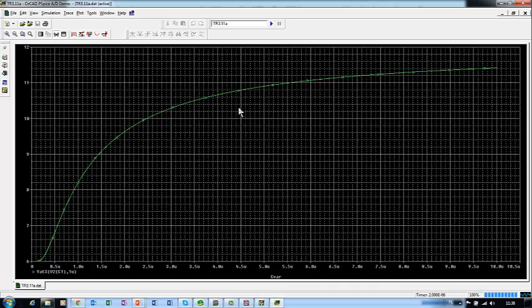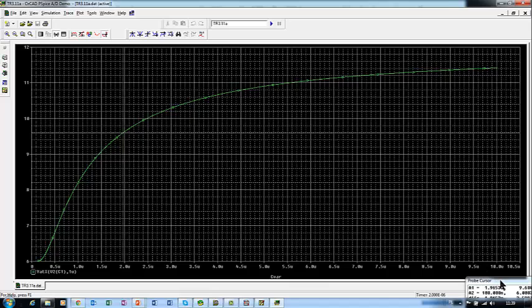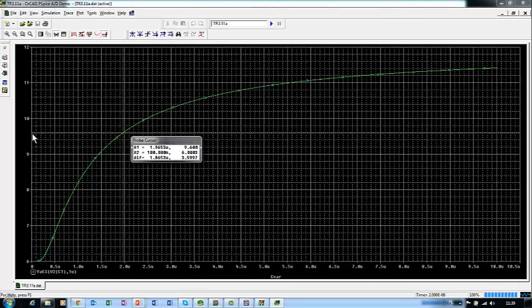Okay, and having this, we have to search for the level 9.6. So here we have a capacitor voltage at 1 microsecond time, and searching for the proper level, 0.8 of supply voltage, which is 9.6. Okay, we find this value for 9.6 at 1 microsecond after changing position of the switch. For this capacitance, we reach this value. Okay, that way we have completed this problem. We have a completed simulation.